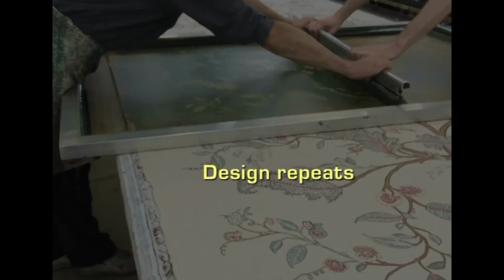Coming to the design repeats, in screen printing, it is possible to have designs consisting of squares, circles and ovals because the areas not to receive the dye are painted out by lacquer. After the screen is completed, it is fastened to the frame. One screen for each color, and the size is large enough to include at least one repeat of the pattern. Screen printing is desirable for the reproduction of large patterns.